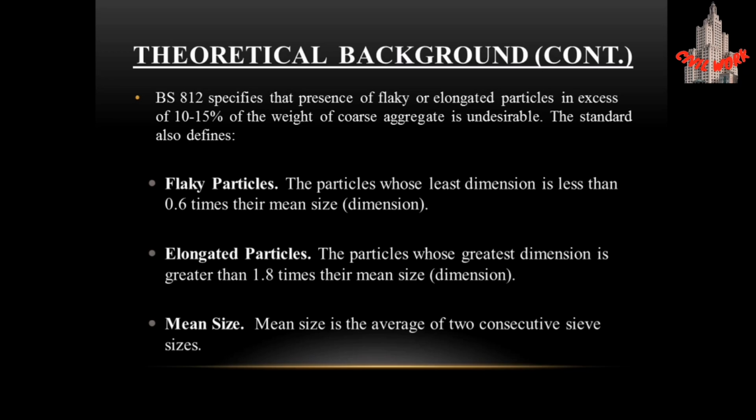Here we have British Standard 812, which specifies that the presence of flaky or elongated particles in excess of 10 to 15% of the weight of coarse aggregate is undesirable. The standard also defines the flaky particles, the elongated particles and their mean size.